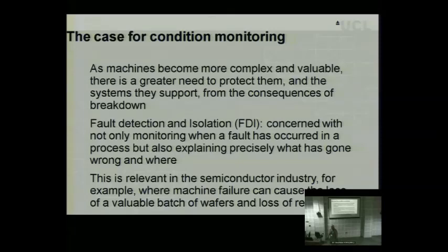Yes. Then how do you isolate that this sensor or actuator is faulty by using unknown input? Yes. Well, I mean, in this particular case, our output Y was a vector. So we had multiple sensor faults. There was nothing that said F0 just acted in one channel. And it could be just the same as the actuator. These are matrices. We have a series of equivalent injection signals.